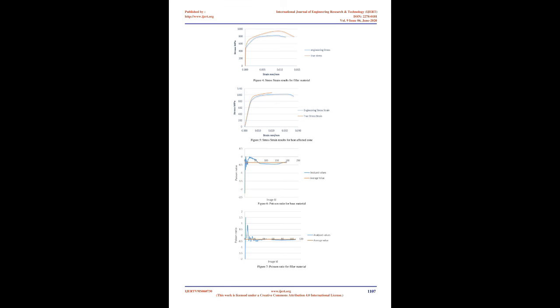Above in Figure 6, Poisson ratio of base material is plotted as a scattered graph showing the values at each image. Longitudinal and transverse strains are obtained from the DIC image analysis. To obtain strain values, extensometers are placed in horizontal and transverse directions. By taking the average of all the values, it can be concluded the resultant value is minus 0.35297, which is close or nearly equal to the value of the stainless steel, which is assumed to be 0.39. And the minus shows the contraction of the material.